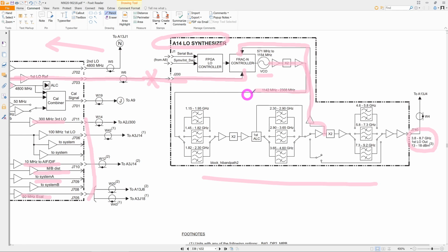And then that signal comes all the way around here, goes into a three-stage, three output switch. That switch is going to be solid state again. It's going to select 3 different bandpass filters, either this one, or this one. And you may ask why again? Well, obviously because they want to get rid of all the harmonics depending on which range of frequency you're operating. This allows you to sweep the VCO and not have some of its harmonics within the band of interest, creating a pure tone. These are all going to be done on the PCB.